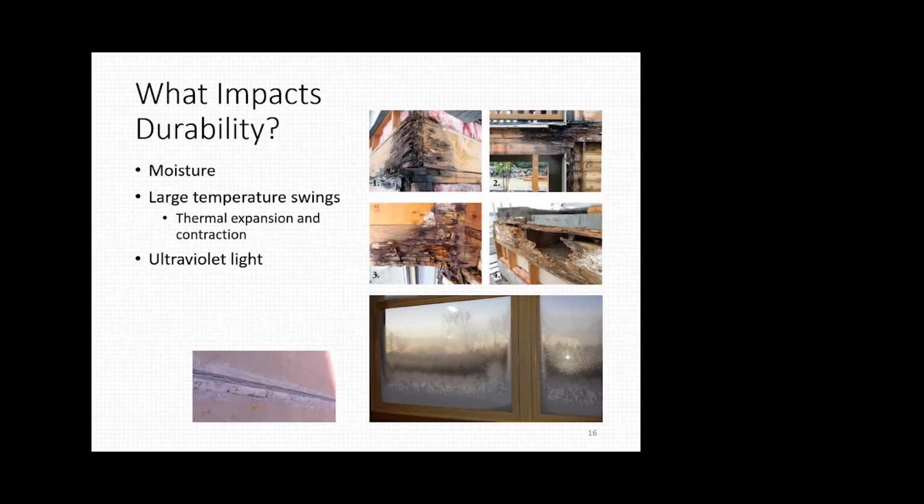I was working in the propane industry. We had a certain type of gas line that was susceptible to ultraviolet light, and code said that we had to cover it in a corrugated drain. When your termination is at the outside of your house and it's this plastic gas line, you had to cover it and make sure it was not exposed to UV radiation, or it would deteriorate and eventually fail.